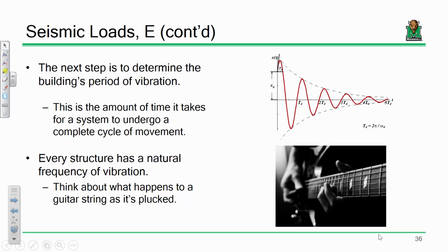So there's 2 points I want to get across with that. The way that you determine a natural frequency is a function of the properties of the structure. In other words, change the properties of the structure, you get a different frequency. The second point is that once it's under free vibration, it all vibrates the same. It's all the same frequency.